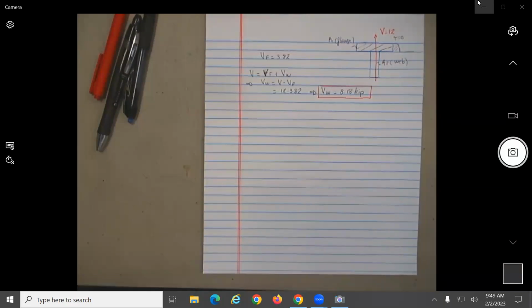So what would be the critical stresses? The stresses due to bending. All right. We say that the shear becomes critical when you have structures that are small and thick. Now, if you want to break it, what do you do generally? You try to twist it, no? Okay. So really, for a long and slender structure, the most critical load should be bending moments to find direct stresses, not really that much shears.